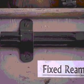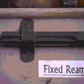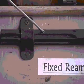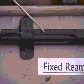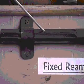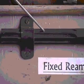While drilling, the hole is created by scratching of the material, but this scratching causes the size of the hole to be uneven. So we use this fixed reamer or the adjustable reamer to smoothen out these holes and to bring it to the exact shape.